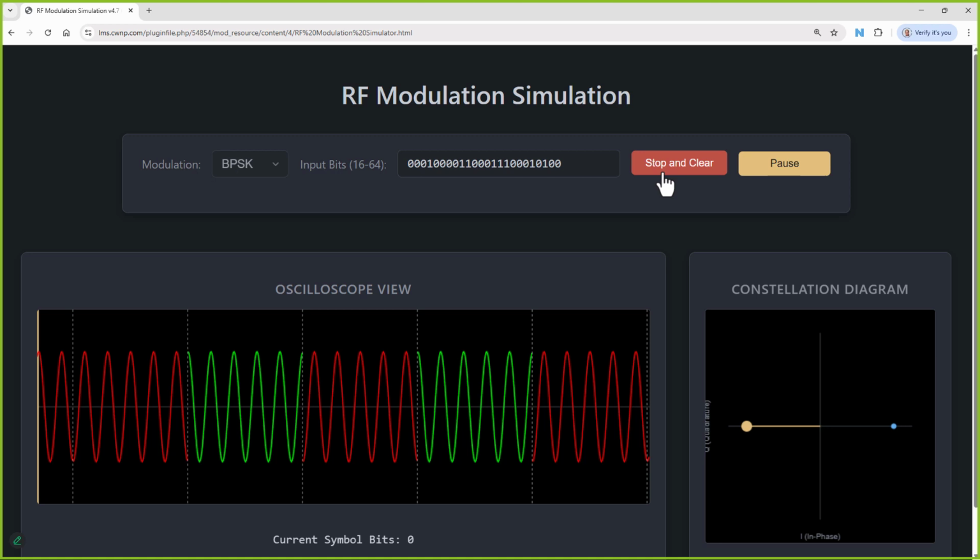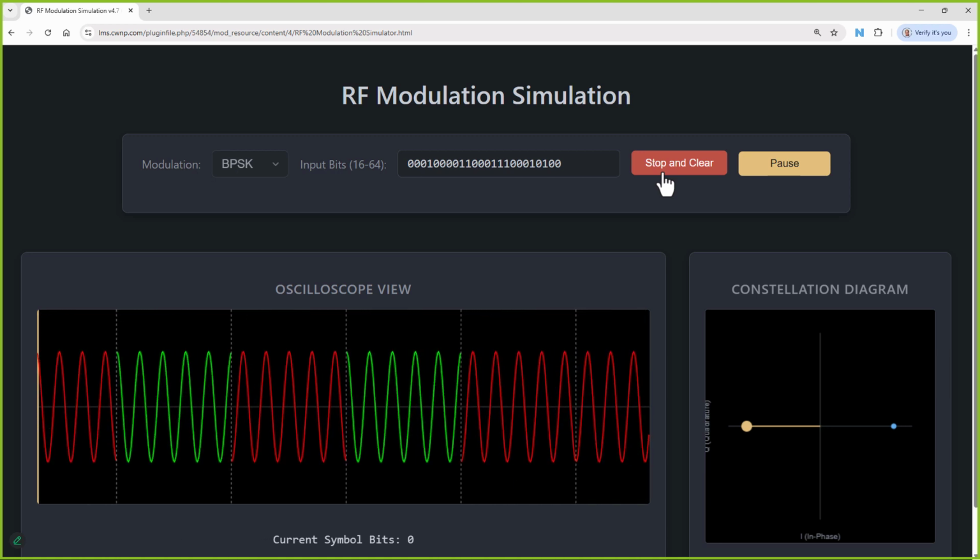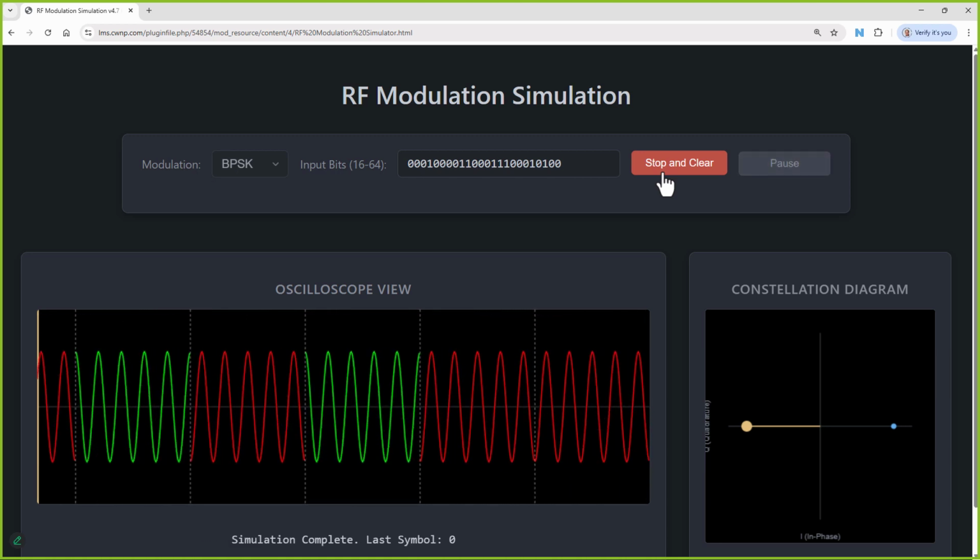Now, because this is BPSK, we only have 2 waveforms, and we'll use a waveform during a symbol period, and then a waveform during a symbol period, and we'll change the waveform in a symbol period if the bit's going to change, as long as the bit's going to be the same. So if it's all zeros in a row, we can keep using the same waveform, one symbol period after another. But if we're going from 0 to 1 to 0 to 1 to 0 to 1, then it will have to change in every symbol period.